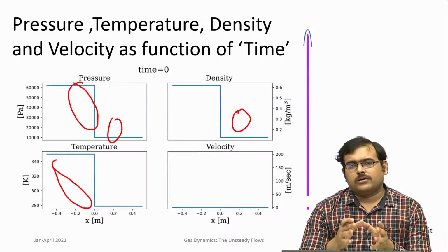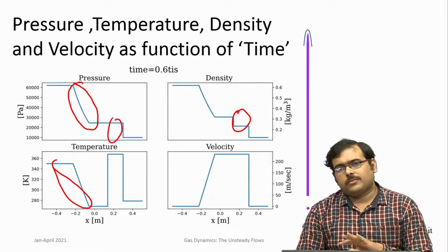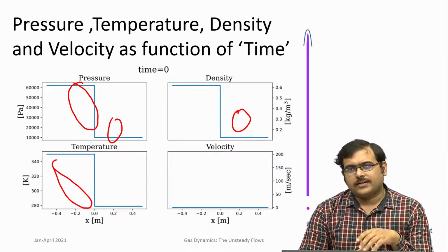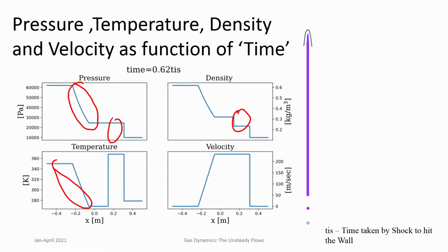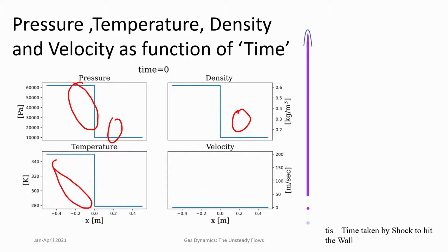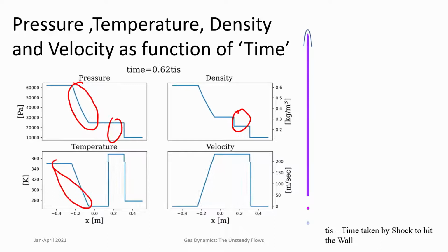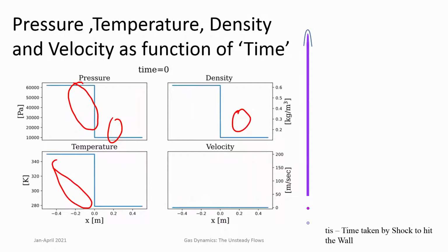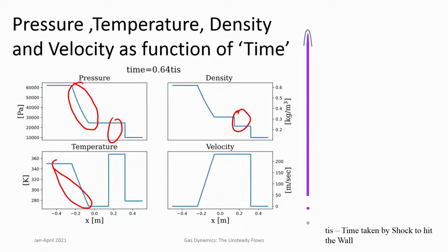Okay, so with this we have looked at the shock tube problem in great detail. It is a template problem for unsteady gas dynamic flow. Several concepts that are important here: moving shock, reflected shock, the boundary conditions across a contact discontinuity, then the analysis of isentropic waves like the expansion wave, and you could also get isentropic compression waves in particular problems.